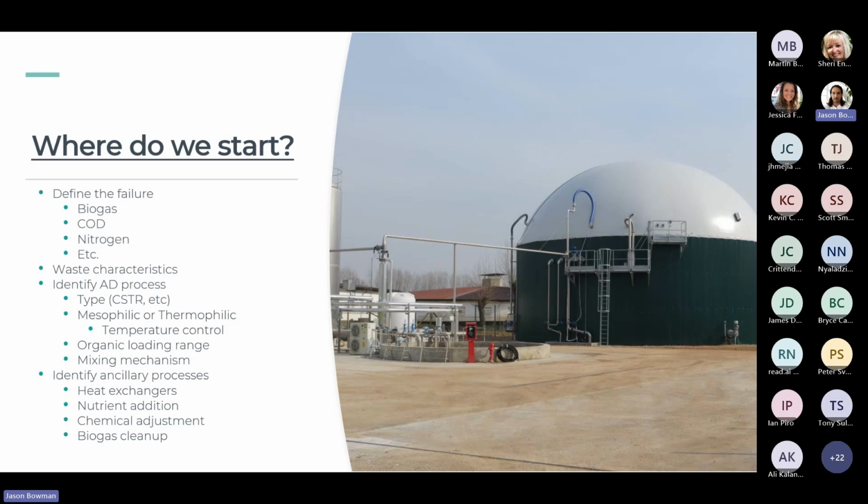inside of the digester. So the point is, we must always understand the mass balance of the organics, the nutrients, the ionic activity, and the ancillary systems to make sure we understand the infrastructure that's on site and how this recuperative thickening process is going to integrate into that. From there, we can evaluate the existing digester volume and the resulting organic loading rates. Once we have a concept of the variability in these organic loading rates, we can determine what biomass inventory we need to control, how much is required, what type of recirculation is required, and if any temperature adjustment is required to stabilize or boost that existing digester performance.